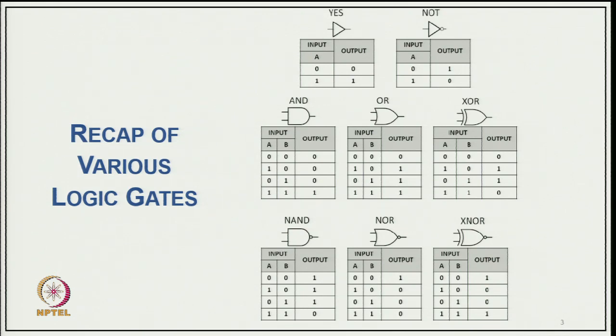It can of course be a multiple input AND gate, we have given an example of that also. Then OR gate, exclusive OR gate, NAND gate, NOR gate, and exclusive NOR gate. So, these are typically the 8 kinds of logic gates which are normally used for realizing many digital circuits, I mean we design based on that, and any expression or many applications we realize with the help of these logic gates. Of course, how we reduce the number of gates and hardware, we have a method we would like to discuss today.